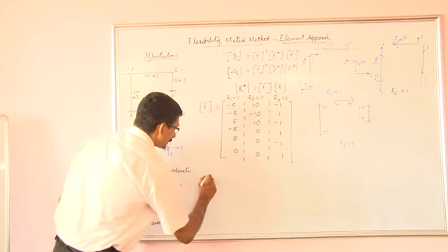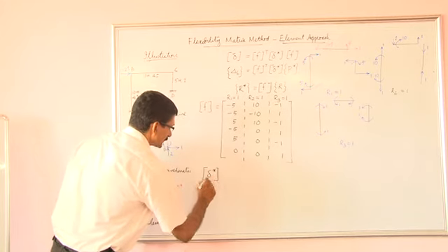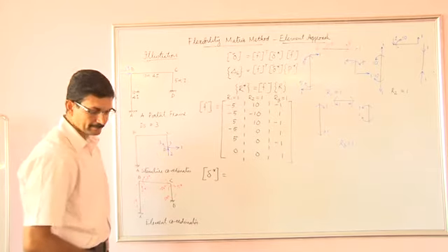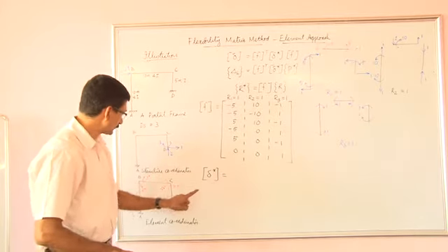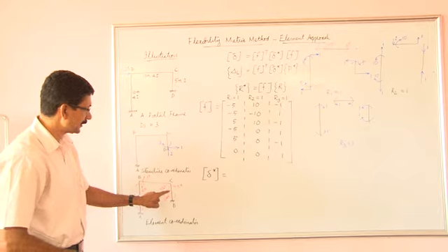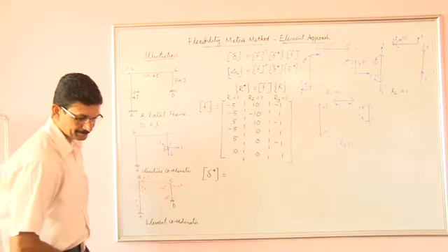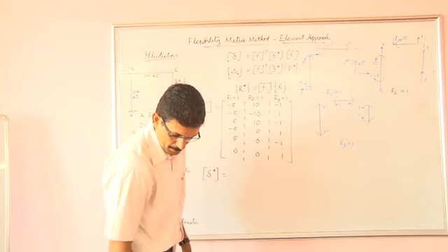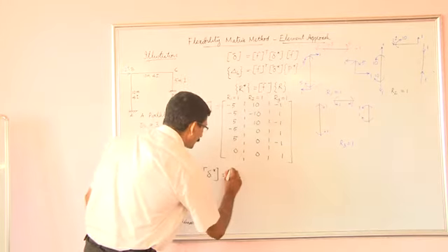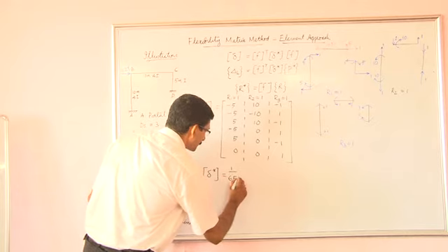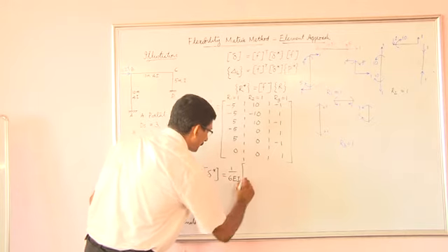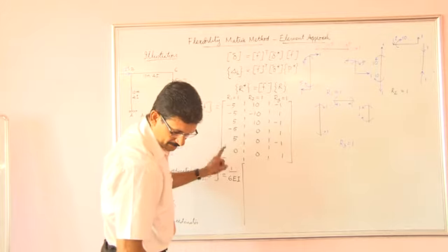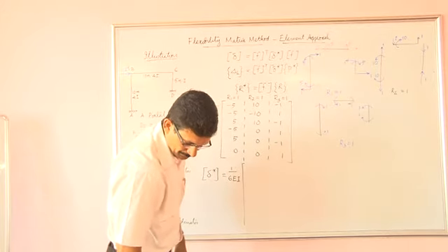Now we can develop the element flexibility matrix as delta star. Delta star will be given by the element flexibility matrix for element 1, element 2, element 3 arranged in a diagonal fashion. So we will get one by 60EI outside, this number would be 5.